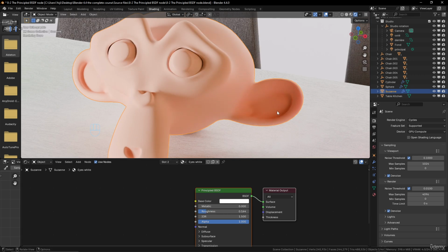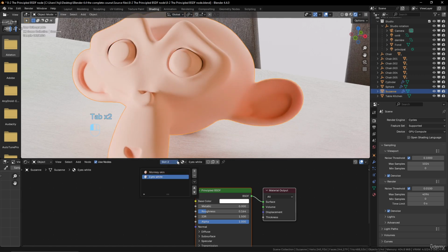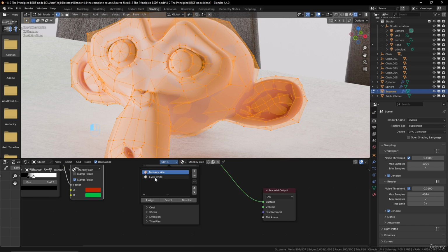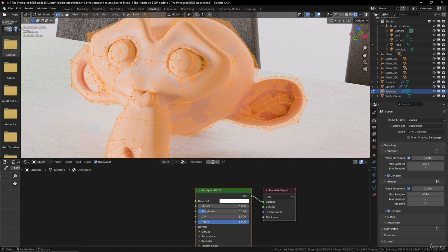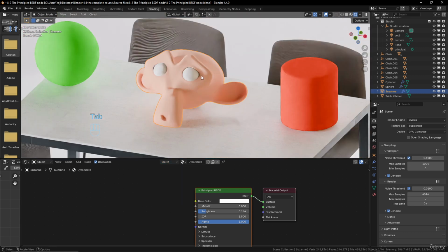And now what I would like is to go in edit mode. And you can see that if I'm not in edit mode, I will not have the buttons that are here, the assign and select and deselect. So now I can select the shader that I want and assign it to a selection that I make. So I know that the eyes with L are something that we can select directly. So I just use this, and now I go into the eyes white and I select assign. And now I will have my new material on the eyes.